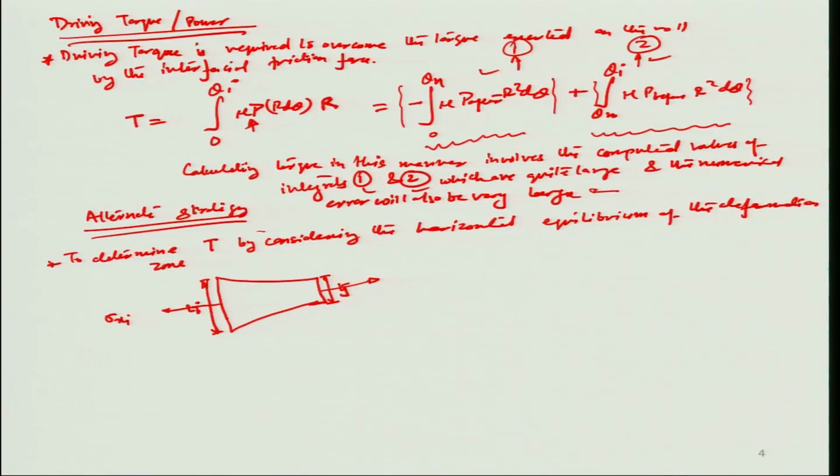One of them is sigma xi, another is sigma xf, and similarly you also have roll pressures all along the way. So the pressure of the rolls are actually perpendicular at every level, corresponding to the curvature of the sheets which are being pressed, and so it will result in some kind of equivalent horizontal force Fe, which can be represented by a cross section of this dotted line with respect to the profile here on both the sides.